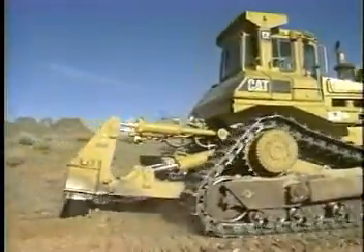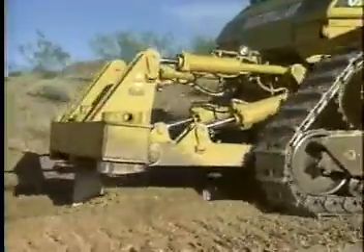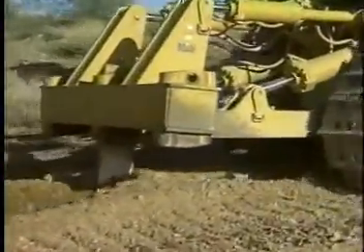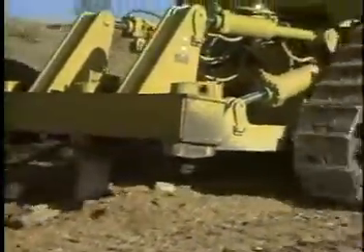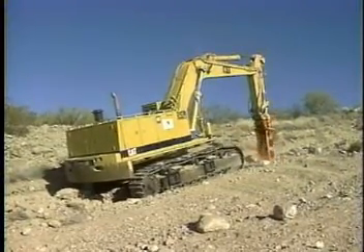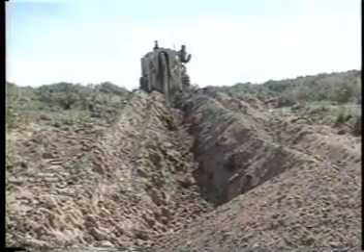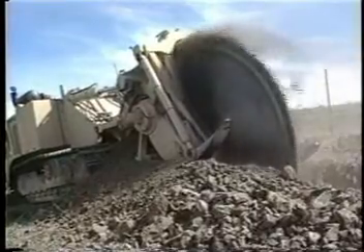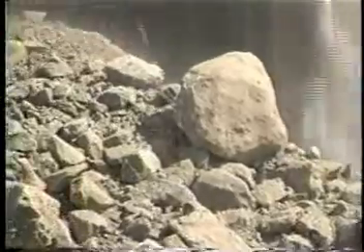In this desert installation, the soil is as hard as rock and requires pre-ripping prior to installation. When rocky areas are encountered, rock chippers move in to break a path for the pre-ripping operation. Only then can a cable plow safely install the cable or duct.